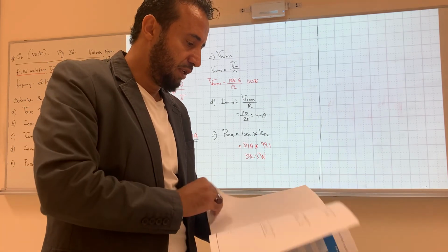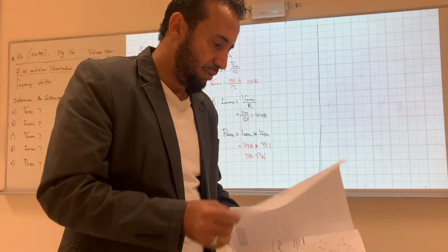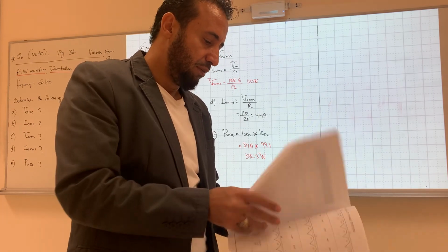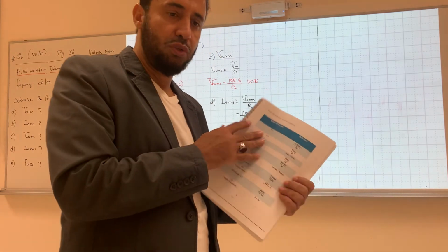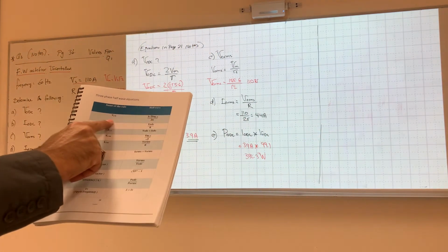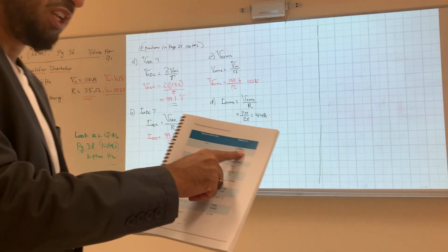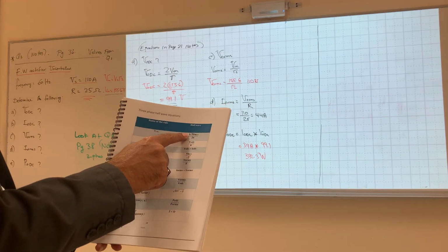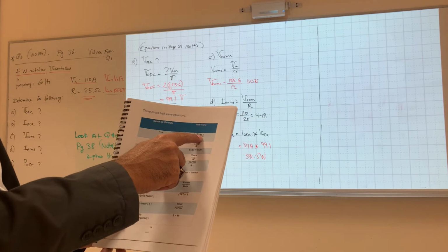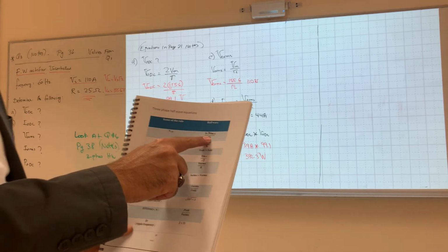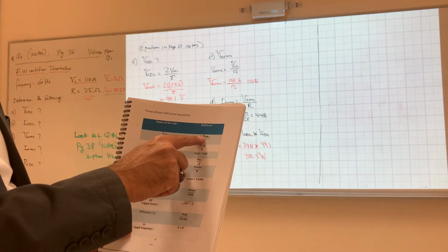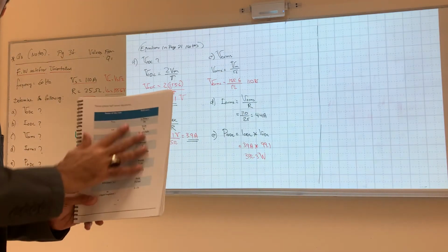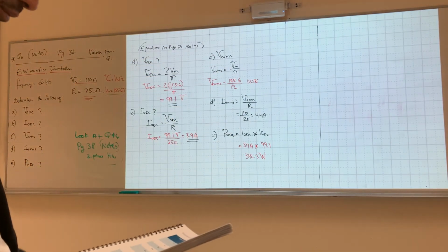3-phase full wave, and the half wave will be in page 27. No, not in page 27, that's the multi. On page 24, okay? So you're gonna use those equations, and we already went over this equation in the theory lecture, which I put as a pre-lab for you guys, which is 3 represents the 3 diodes, and the square root of 3 times Vmax line to neutral, because we connect the 3-phase to neutral. That's why we have square root of 3 times Vmax line to neutral divided by 2 pi, which is 1 cycle, and the rest are Ohm's law, same as what we explained before. Okay.